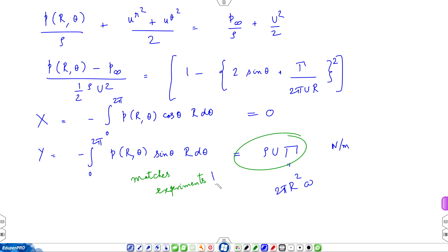So, the first advantage of studying potential theory is it helps you determine lift. So, for lift calculations potential theory can be used, that is the first observation. But drag is 0: you flow past a cylinder and at high speeds drag turns out to be 0, which is a disastrous result. But I gave you a hint that with a little bit of tuning of the pressure field, it is possible to obtain results for non-zero drag.